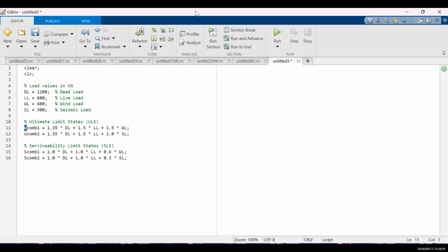Okay, so from this summary you figure out that the wind loads have a higher impact on the building than the seismic loads, right? You can see every single time the safety factor of the wind load is bigger than the one for the seismic loads. And the snow load is going to be the same also. The snow load is going to be less than the seismic loads, right? So this is how we can do the load combination. I'm just going to print the results and then explain everything properly again.